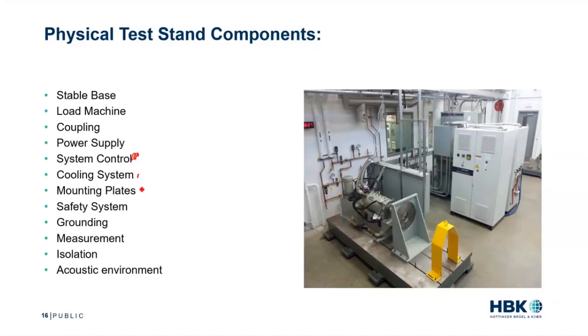Mounting plates, again, this is an important one for torque ripple testing, and it's boring, but it's important. And also NVH testing. We want to have a very heavy, again, large mass mount that connects to the base plate and very rigidly connects to the base plate, so that, again, we can eliminate the parasitics, and we'll speak about this a little bit more, but you want something that you can very reliably mount the machine to, so that you're eliminating outside sources of noise, vibration, torque ripple, or in the case of torque ripple, you really want to make sure you're getting the information coming from the machine and not from any external sources. And you don't want it to be multiplied or hit a resonance point anywhere, so just having a big, heavy mount that's well secured to the base.